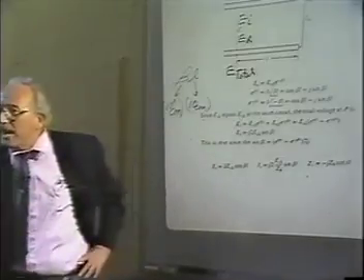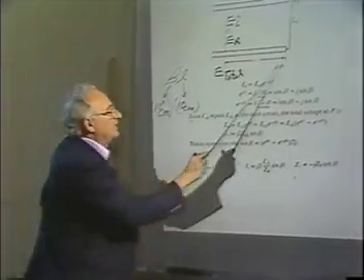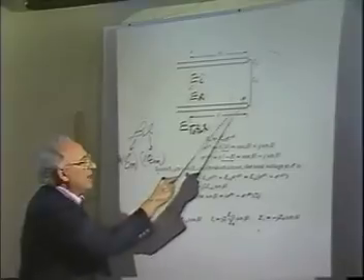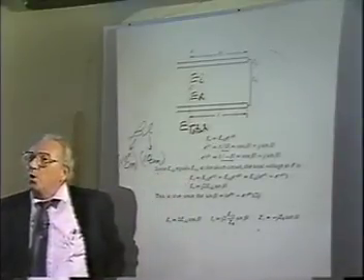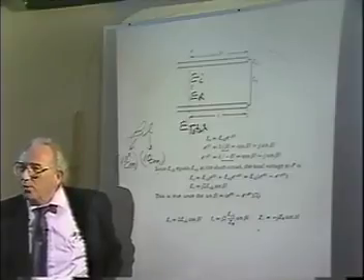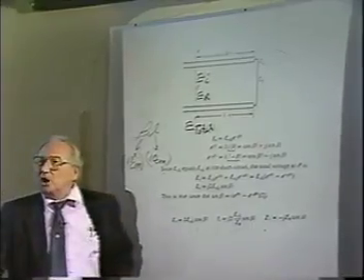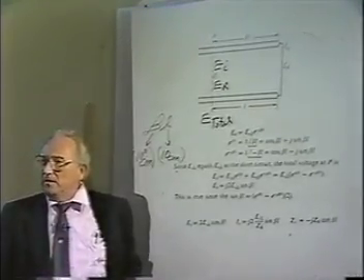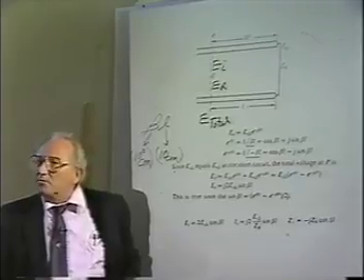You're referring everything to the load impedance. The reference is this reference plane here. The load is the reference. Everything going back in this direction is in the negative direction, going toward the generator from the load. Okay? Now you'll find out that on the Smith chart, since it's toward the generator, what kind of rotation will that be on the chart we just looked at? Where was the generator? What was clockwise or counterclockwise? Clockwise, wasn't it?